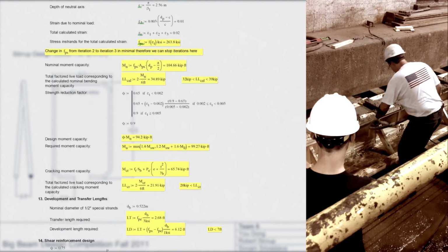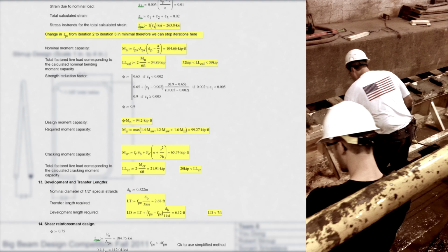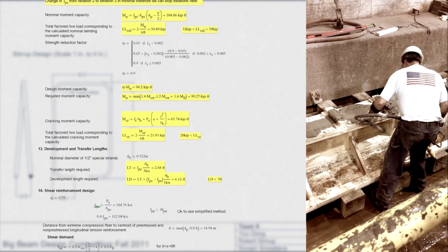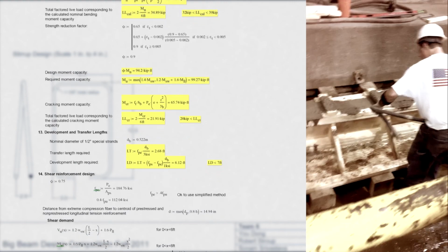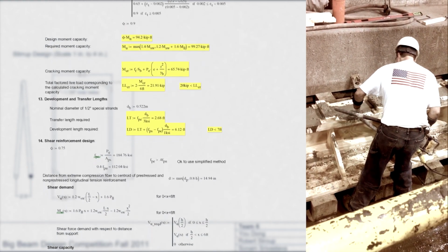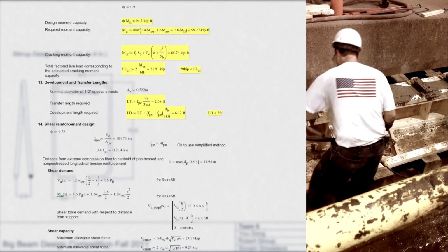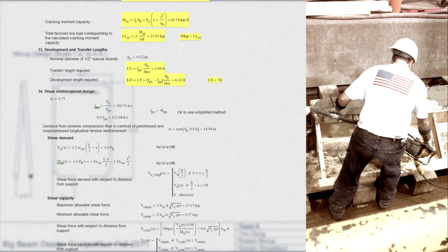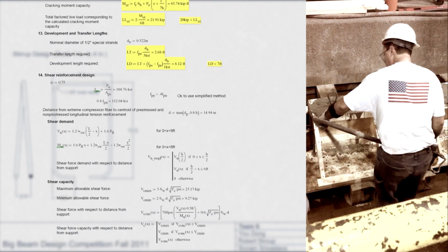Our reduction factor decreased by 1/100th of a percentage, and our effective load resulted in a total of just over 62 kips. After calculating our losses, we then checked the ACI allowable stress requirements on the final section. For the transfer stresses at the support and midspan only, our initial transfer stress at the support exceeded the allowable limit.